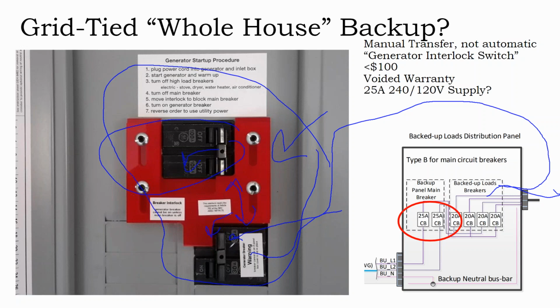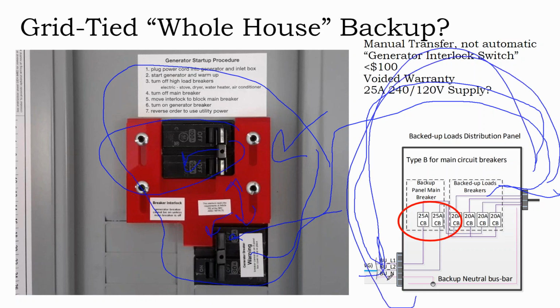Now, there's a lot more assumptions in there that you have to make. You have to have a battery. You have to make sure that the inverter is not backfeeding itself, which will just waste a bunch of energy, if not burn the inverter up. So you might have to have another breaker that turns off. This is kind of advancing solar design.